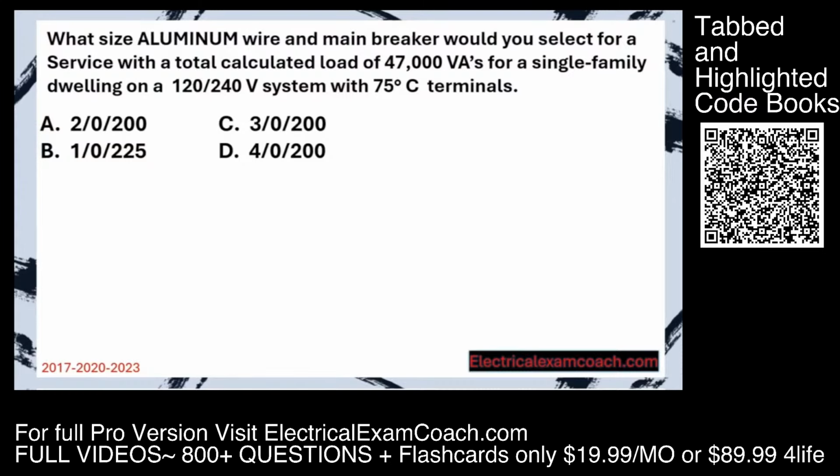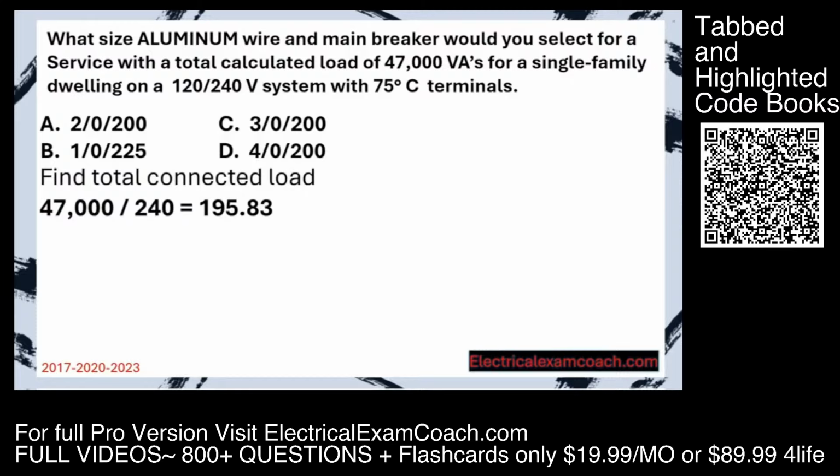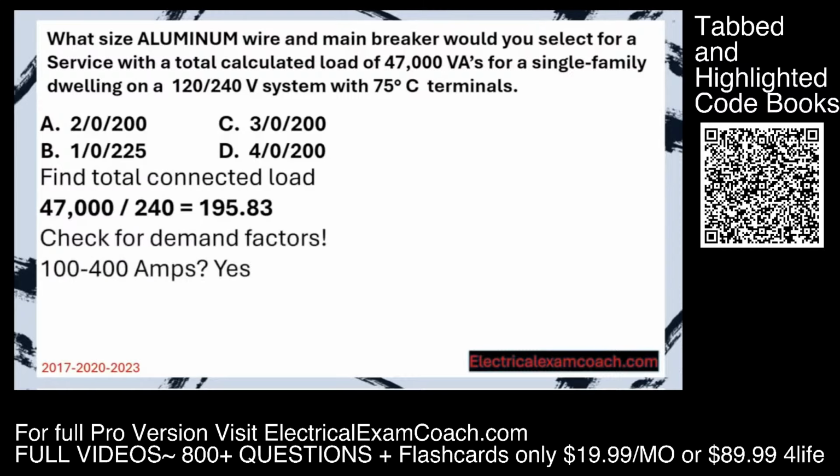What size aluminum wire and main breaker would you select for a service with a total calculated load of 47,000 VAs for a single family dwelling on a 120/240 volt system with 75°C terminals? Step 1, we're going to find our total connected load. In this case, they've given it to us, and we're just going to divide, just like we did before. Now, we check for demand factors. Is this in between 1 and 400 amps? Yes. Is this on a single family dwelling or the individual unit of like an apartment? Yes. So, the 83% rule does apply.